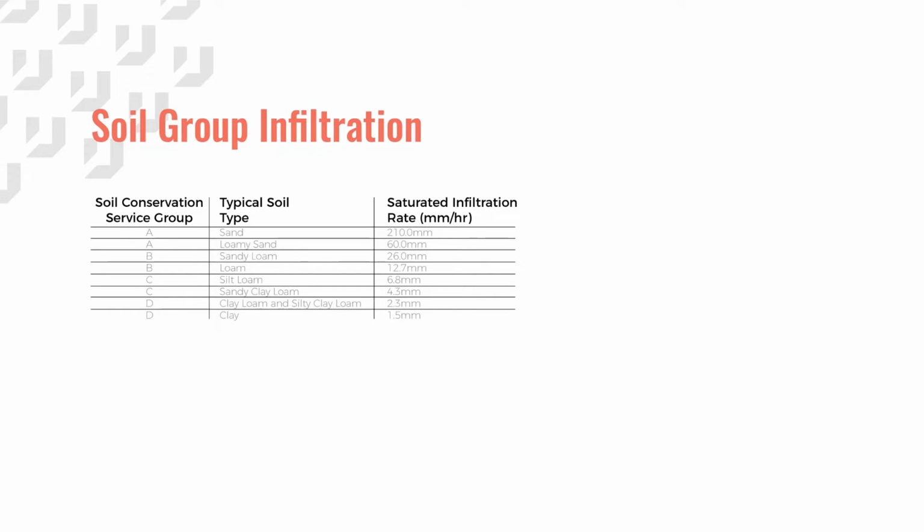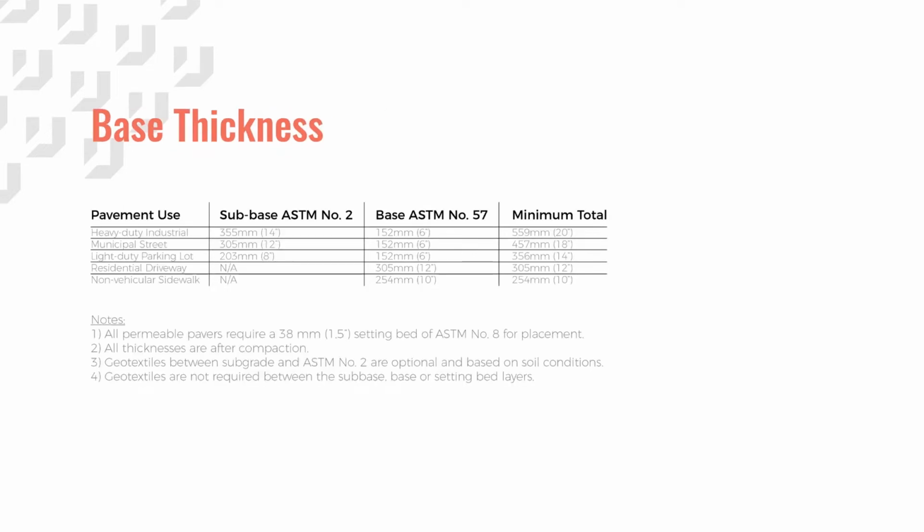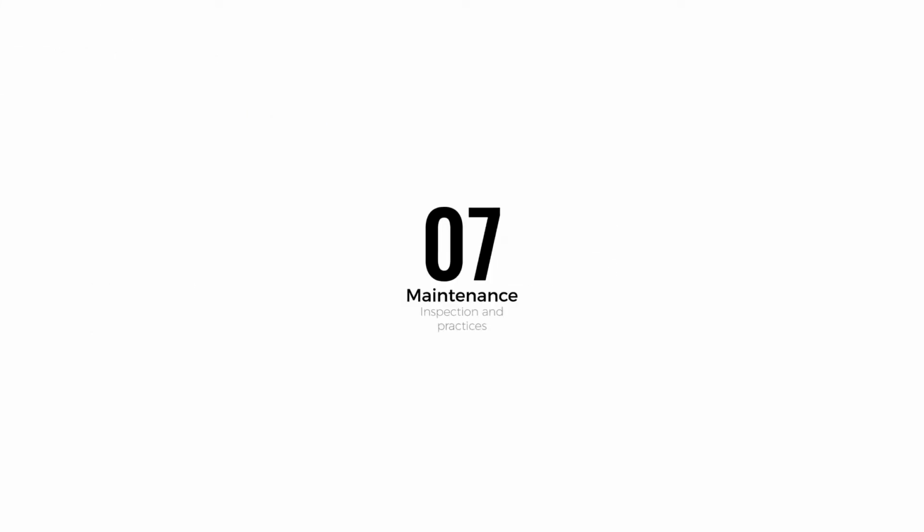Even poor soil with a low infiltration rate will work. For example, a soil with 0.25 inches or 6 millimeters per hour of infiltration will have complete infiltration after 4 hours of rainfall. Permeable paving is not a typical segmental pavement. Unilock recommends that a professional engineer design a site-specific plan based on available site information. Along with information provided in this presentation, Unilock offers all the data on our pavers necessary for a successful design and implementation of a permeable unit paving system.